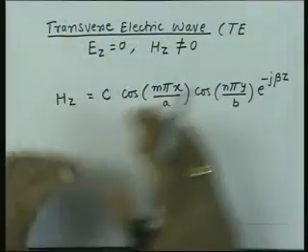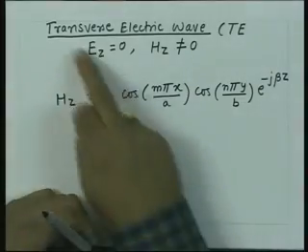So, these fields have the variation which essentially we are looking for, the tangential component of the magnetic field must become maximum. Using this expression for Hz, now we will investigate the transverse electric mode and see the characteristics of the transverse electric mode and then compare the behavior of this mode with the transverse magnetic case. So, we will continue the discussion on the transverse electric and transverse magnetic modes inside a rectangular waveguide and see more properties for these modes.